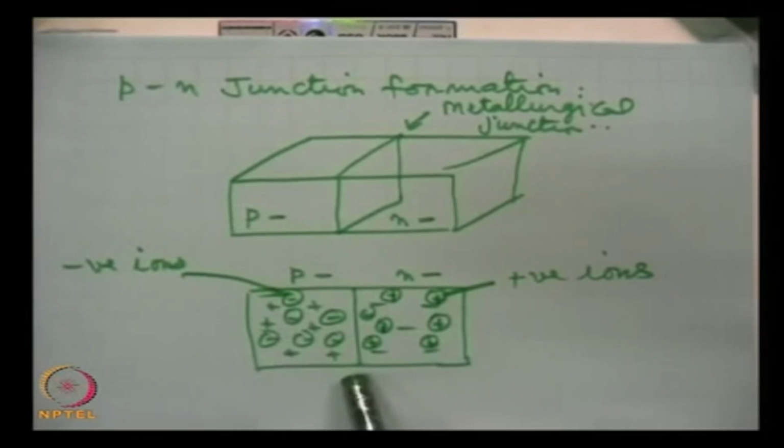That means, if we take a p type crystal separately, n type crystal separately, and just glue them together, then this diffusion will not occur because the physical barrier will be so high that it will totally stop the diffusion processes. A p-n junction cannot be formed. So, remember, a p-n junction will be formed wherever n and p semiconductors are present simultaneously together and there is a structural continuity.